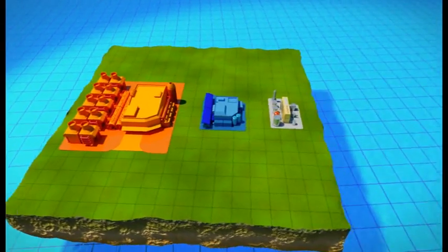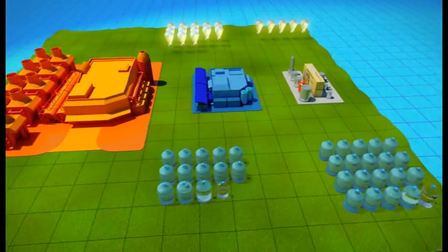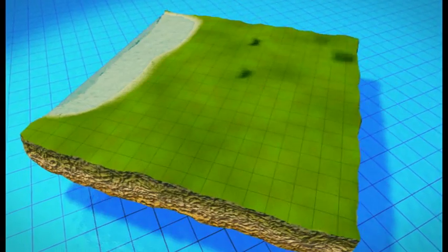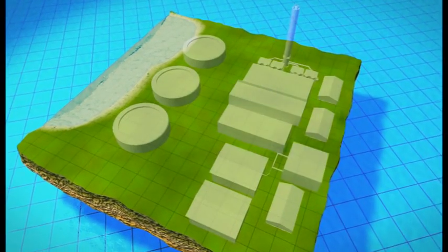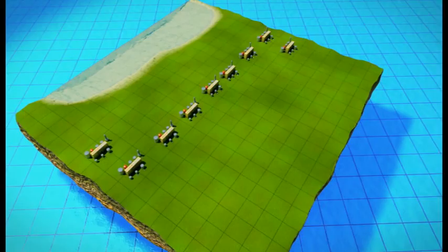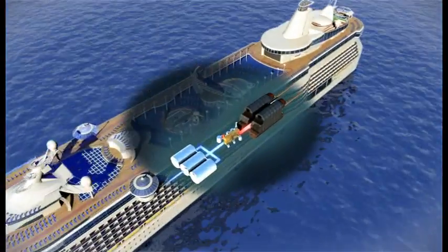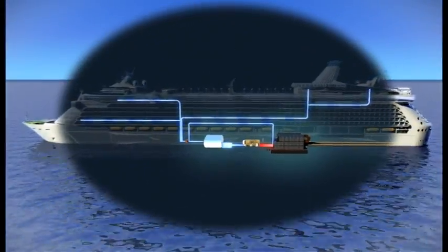Memstil plants are modular and are more compact than traditional desalination plants. With the use of low-grade heat for desalination, the energy requirement for Memstil is much lower than current techniques. The Memstil modules can also be configured to suit capacity and space requirements. The integration of Memstil into the freshwater system on board ships using waste heat from engines is a convenient way of supplementing purified water. The potential uses for the ultra-pure water derived from Memstil technology are endless.